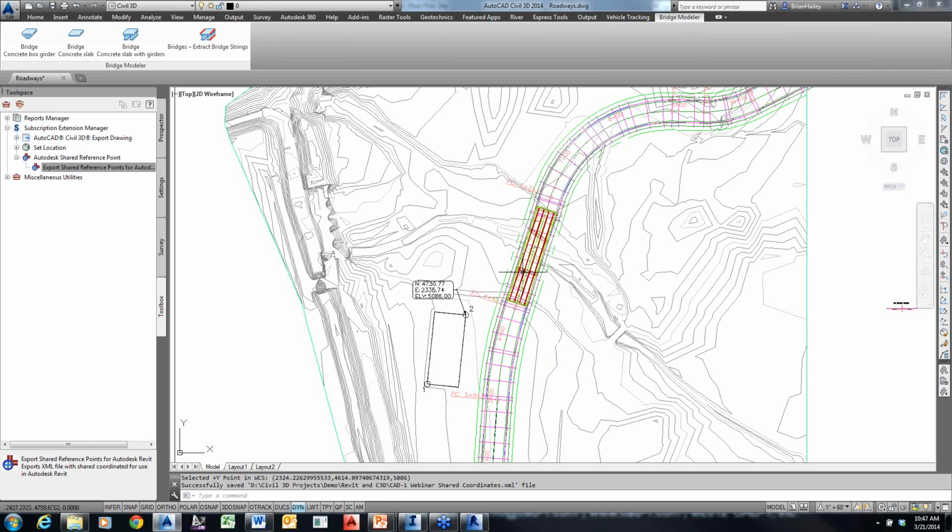So Brian asks, so in Revit it can triangulate any way it wants? Well, basically it just goes through the basic Delaunay triangulation method. It draws circles around the points, and it triangulates between circles that don't have any points in them. So if you're interested in the way that it triangulates, go check out Wikipedia, do a search for the Delaunay triangulation method. It'll make you the hit at your next party. Right? You'll be, hey, did you guys hear about the latest with the Delaunay triangulation method?